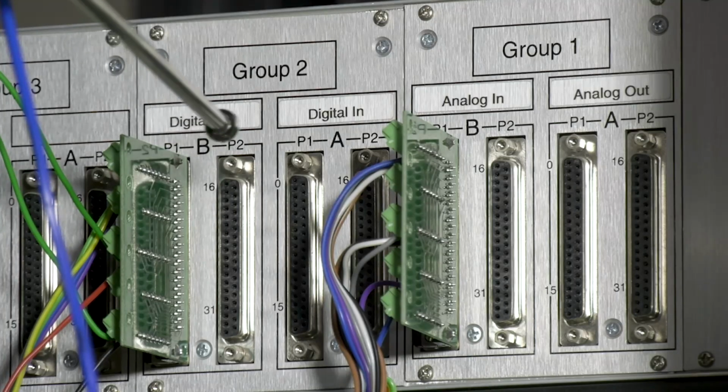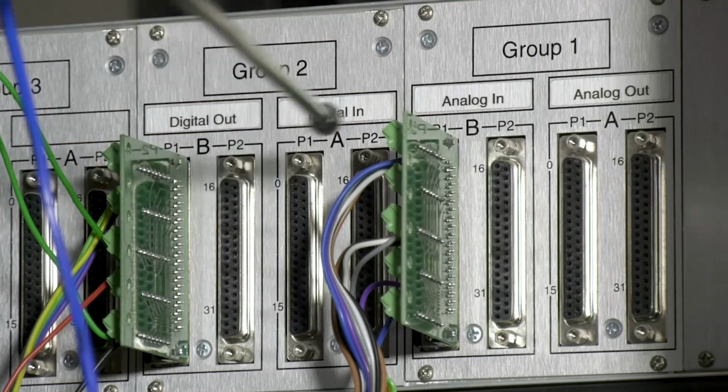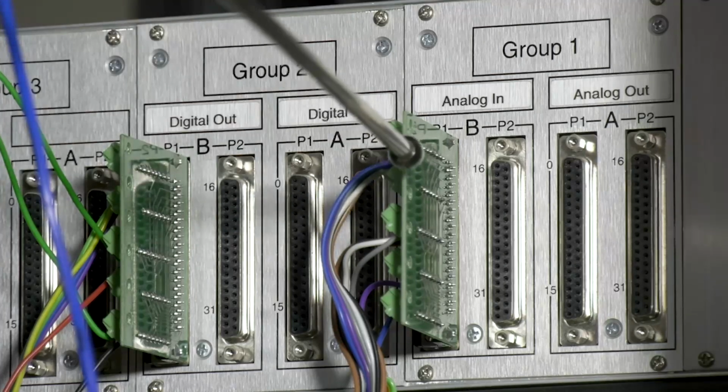The output and input voltage range of analog pins is plus or minus 16 volts. Accordingly, the voltage and current sensor circuits are designed such that their output voltage range does not exceed the voltage range of analog input pins of the Opal RT under any circumstances.